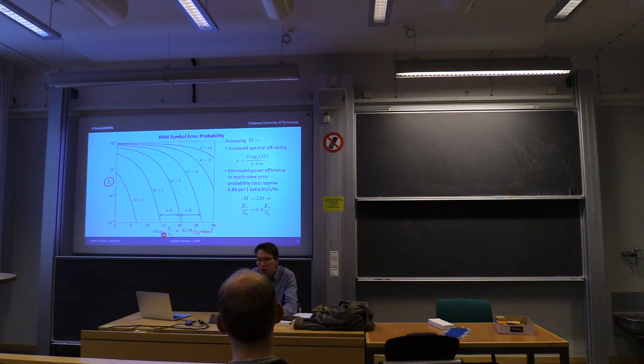And if we take the 10 log 10 of that, we get this in decibel scale. So this is in dB. I mean, it's a dimensionless unit here, so it doesn't have a unit, but when we plot this in logarithmic scale, we take 10 times the log of the SNR, and then we get it in dB.